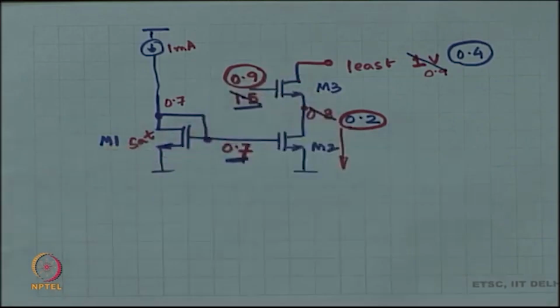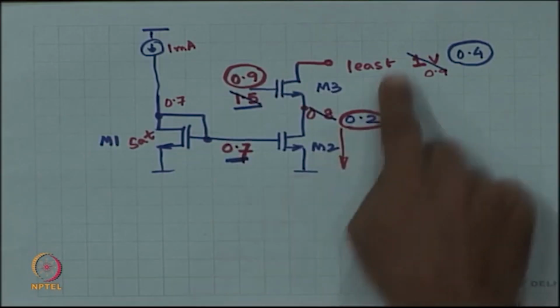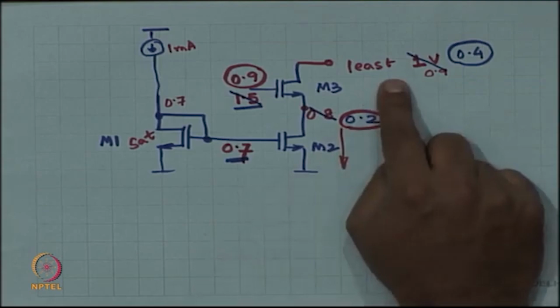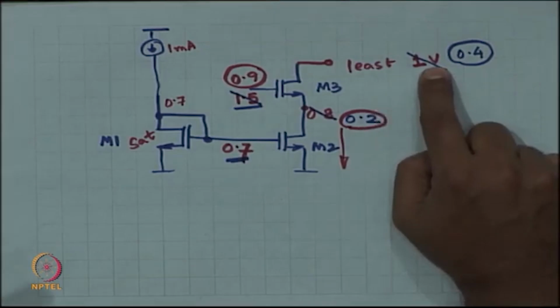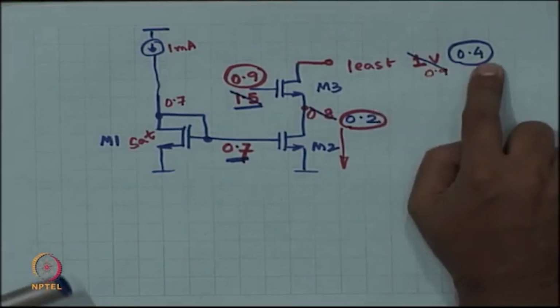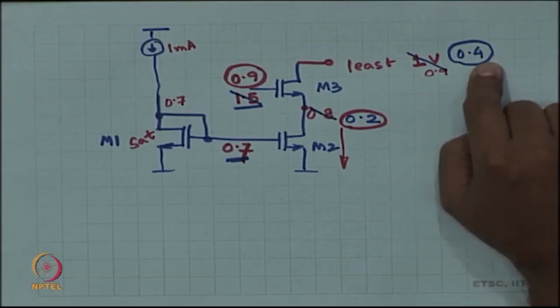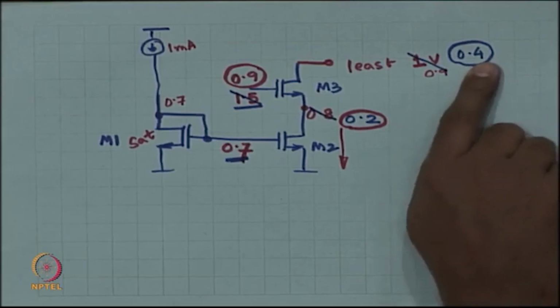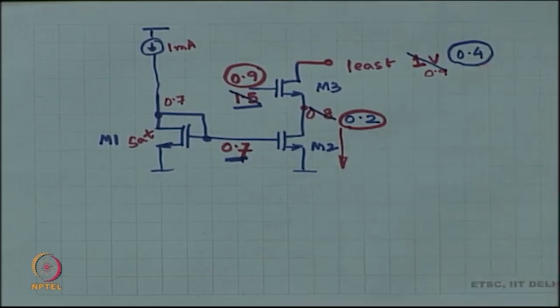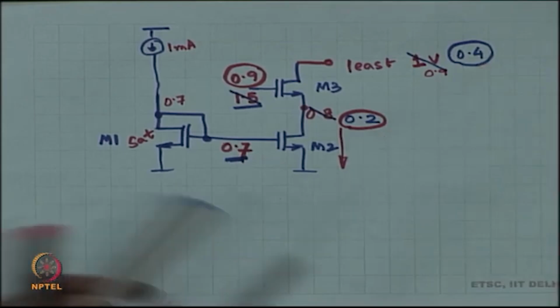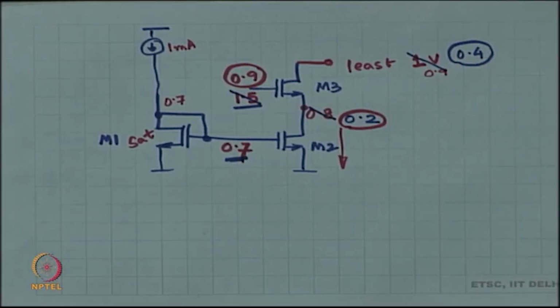On one case you have a positive, an upside, right, that you have got graceful degradation. On the other hand, you have a downside that the range is much more limited, right. And in this case, the upside is that the range is much more, the voltage range, the headroom is much more. However, there is no graceful degradation. As soon as you cross below 0.4, you are done for. Okay. So, these are the pros and cons.